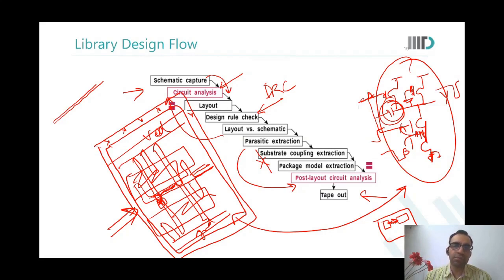Okay, sir. So after layout, if we check any output, for example, we have done a CMOS inverter in our refresher, so after layout, if we take the output, would the output include the parasitic extractions, the capacitance? It will include it if you have done the extraction and embedded the capacitances into your netlist. If you're doing the post layout circuit analysis, it will include. If you made the layout, left it there, and then you're redoing the simulation of the schematic again, then no change.